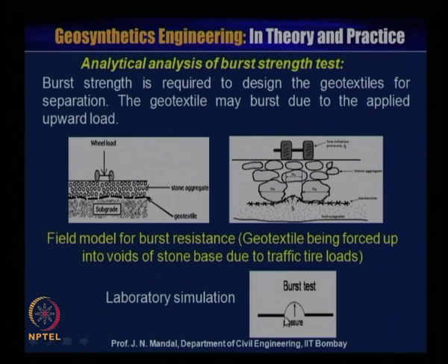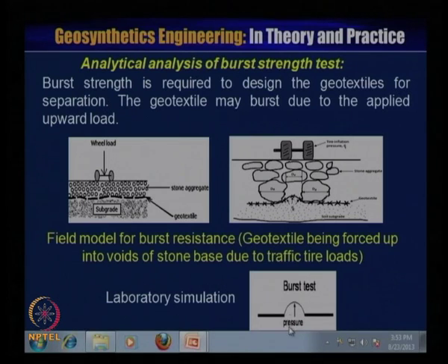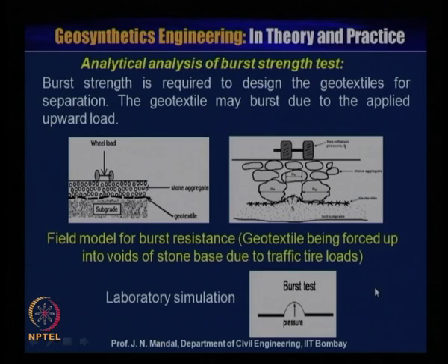So, you can clamp it in a model, and you can see this geotextile material may push upward, and then the geotextile material may fail. So, this way we calculate the burst test.